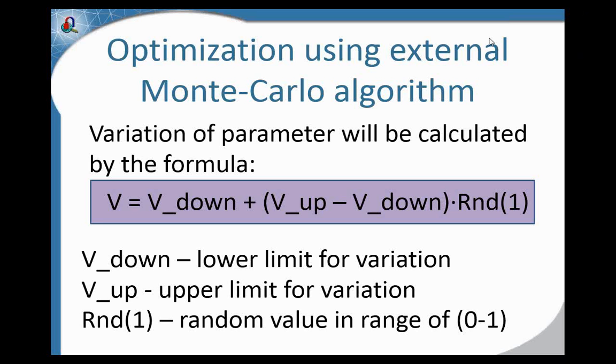There are just a few lines of code needed to implement Monte-Carlo optimization. We highlighted 4 logical blocks in this script: declaration of values, reading of values from the spreadsheet, initialization of values, and the cycle itself. And in this cycle, random parameters are generated, and LabelMover runs QuickField and extracts the result for these variations. In fact, the essence of this code are three calls to LabelMover. Let's take a look at this code.